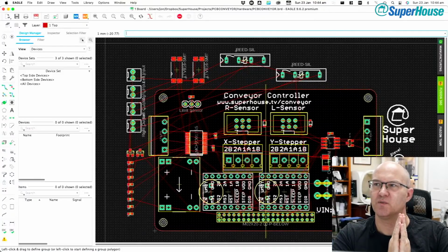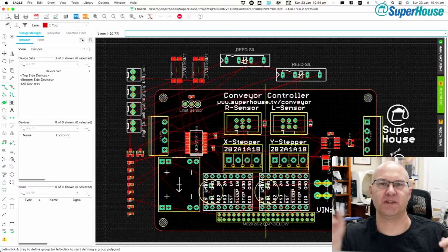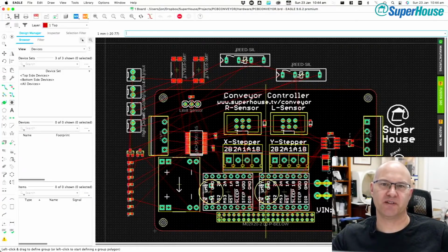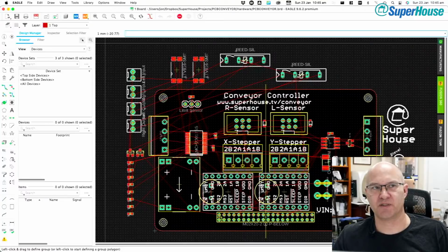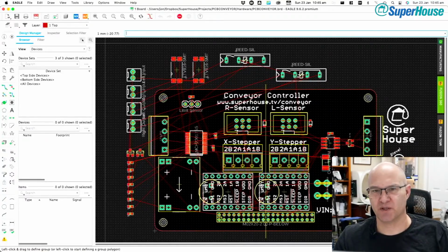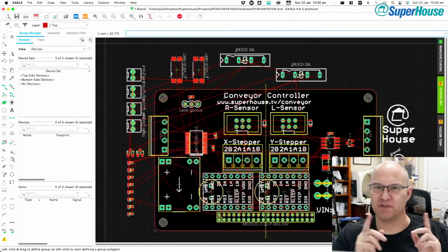So what I want to do is switch to stepper motors for driving the actual conveyor belts. And that means that I will have more accurate speed control. I'll be able to calibrate it and say, I want it moving at 400 millimeters per minute, or that sort of thing. I can match it to whatever the devices are that it's joining. And it also means that I'll be able to have a board come on and then move it to a precise position and then stop it, because I know how many steps it takes to move to that position. So anyway, that was the kind of background story.